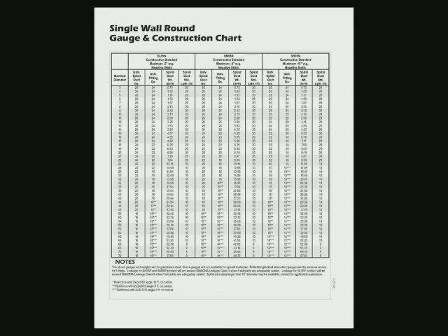In this particular case, we're going to be at roughly 4 inches of static pressure, and we'll get into that in a minute. So with that said, we would recommend that you use the SMACNA negative 10-inch pressure class duct. It's a little bit heavier than the other negative 2 or negative 4 inch pressure classes, but you need that just to be able to handle the negative pressure in the system.